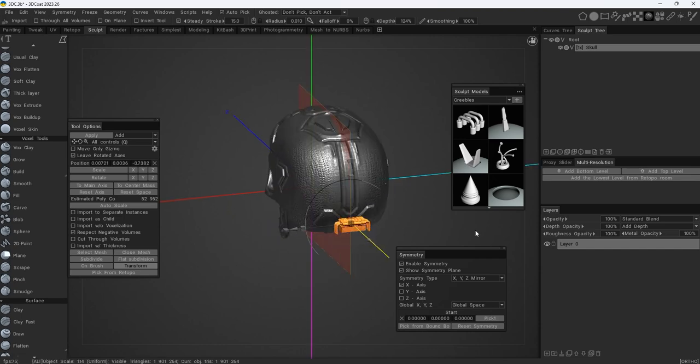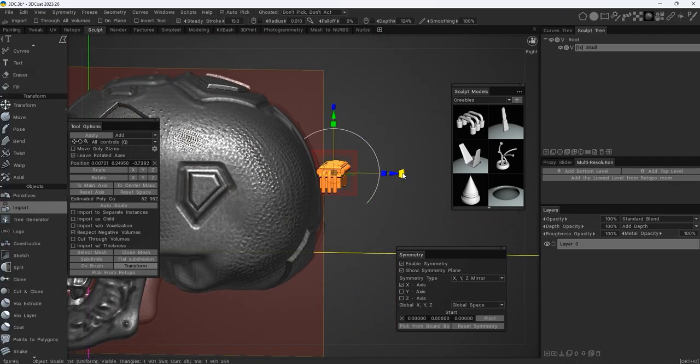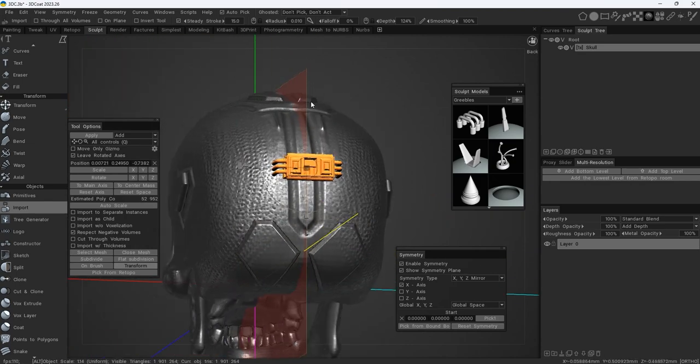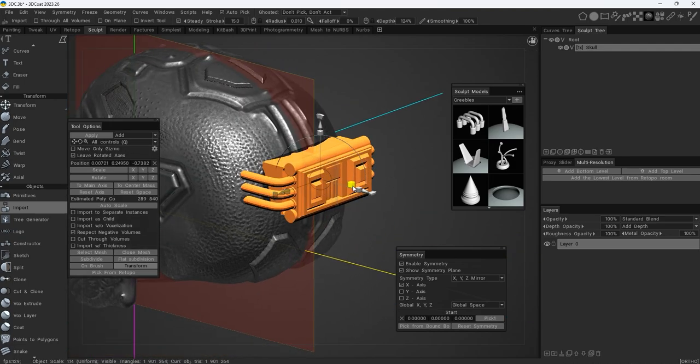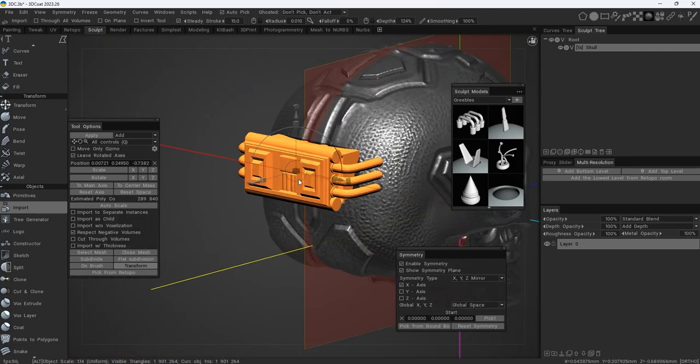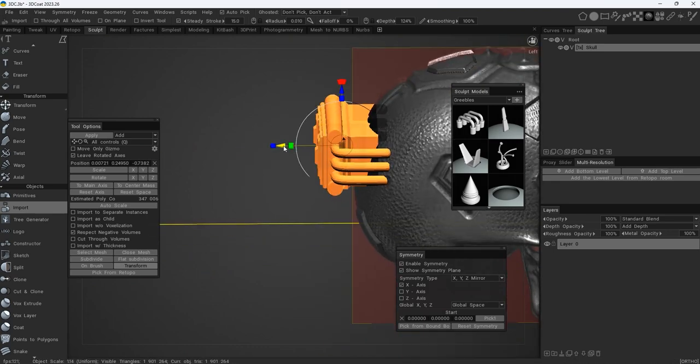So now let's move this geometry to the right position. Rotate this one, and you can hold on your control key so that the rotation will be based on 90 degrees, 45 degrees, etc. Let's enlarge this one. Okay, pretty nice. Let's move this one inside.